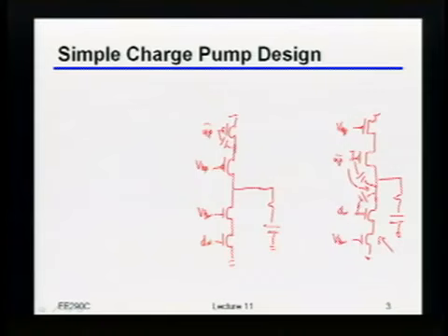So anything else you might be able to hack on this thing to make sure that, in this particular case, VDD doesn't make it so easily into the output? What do you guys think? With the cap to VDD or? Cap to VDD. No, well, no, wait. I mean, if you flip the cap over, then you've changed what the reference is, right? So yeah, maybe coupling to VDD is not so bad, but then coupling to everything else is kind of bad news, right?